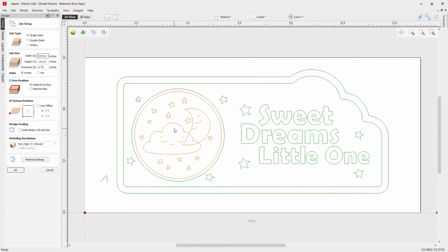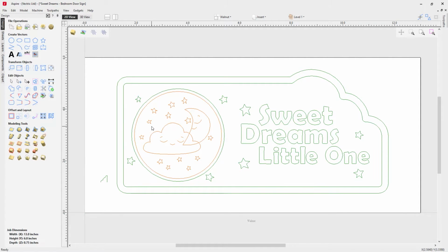Or in the future, if I decide to make a little bit more detailed model, I definitely wouldn't have enough pixels. So this kind of a setup using a custom sized sheet for the job that you'll be modeling is an important sort of workflow thing you're going to want to think about as you're going on your 3D modeling journey. So we're just going to go ahead and click cancel here.